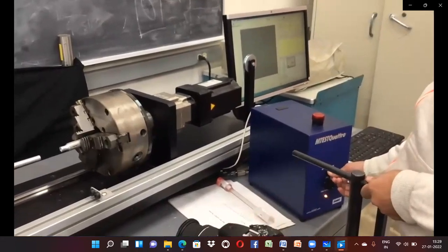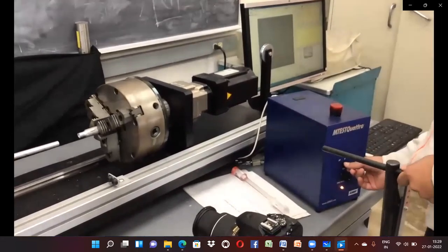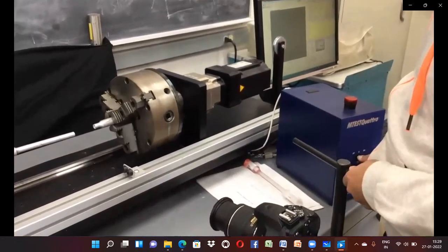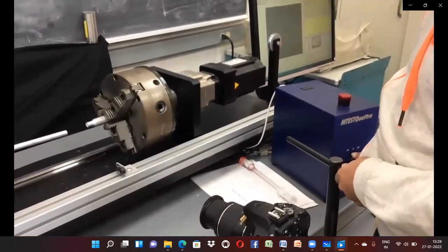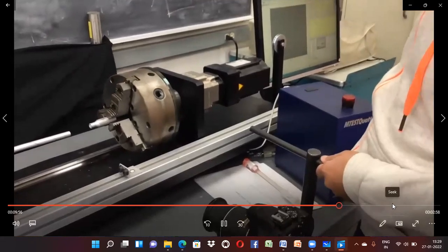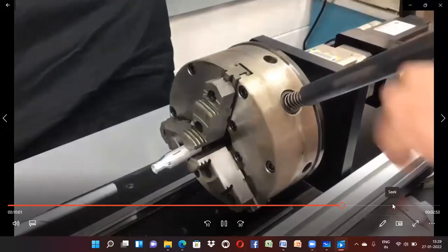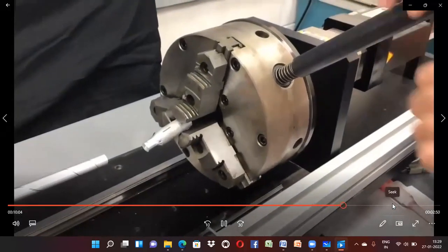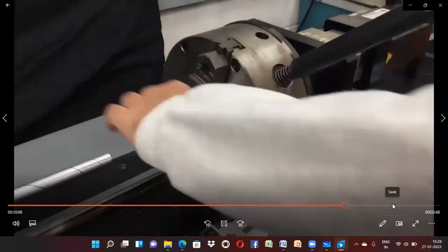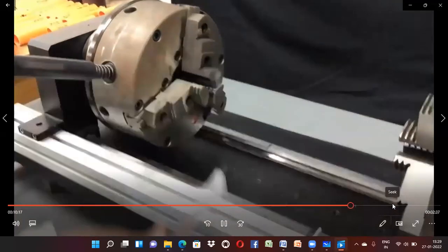So now you can jog it. There's a high-speed jog and a low-speed jog on this thing. He's going to use the high-speed jog, jog it around until he has access to that square keyhole. And then he'll use, of course, the spring-loaded safety key to loosen that thing up, and he can get the specimen out of there. You can see the spring there. Very important to use a spring-loaded one in the machine shop, a little less important here. So there's the short end, the proverbial short end of the stick, and you can loosen up that end.